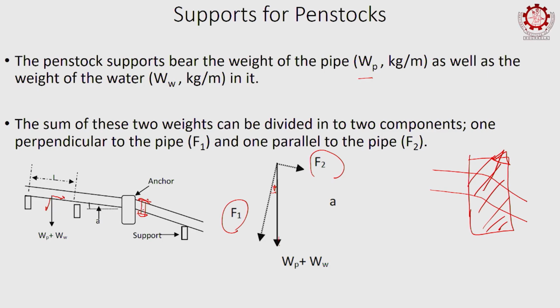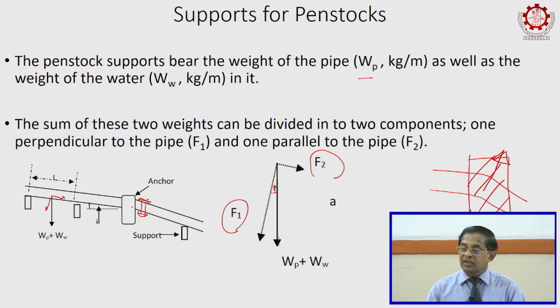Theoretically there is an opening or gap in the pipe ends, and leaks are prevented by seals, water seals, in the expansion joints, and thereby when the expansion requirement occurs, the pipe can expand upward. The amount of gap will be decided depending upon the expected expansion. So, expansion joints are there.